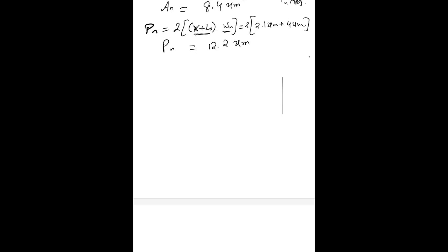So what we can do here is, we can now solve the expression for C of N. If we put the values back in for C of N, first we have to write the value of Cj for NMOS, which was equal to 86 femtofarad per micrometer square.